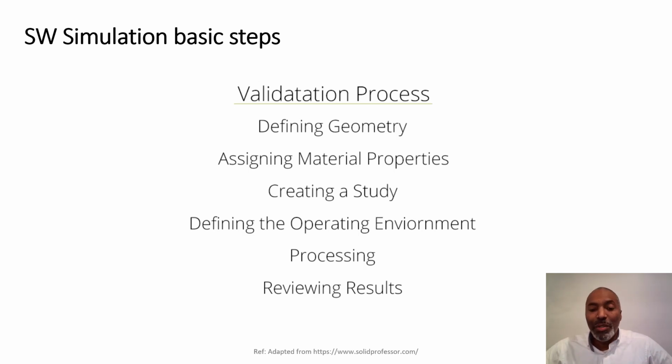So let's say, for example, you wanted to know whether or not a part would fail under a given load. Now, do the results give you some measure of the von Mises stress compared to yield, so you can actually make that comparison? If you can't, then maybe you need to go back to basics on your simulation and figure that out. You just have to make sure that the questions you're asking of your model can be answered by the model that you have built. And it's pretty much like that with any software. The user has to define what they want because the software is only going to do what you tell it to do.